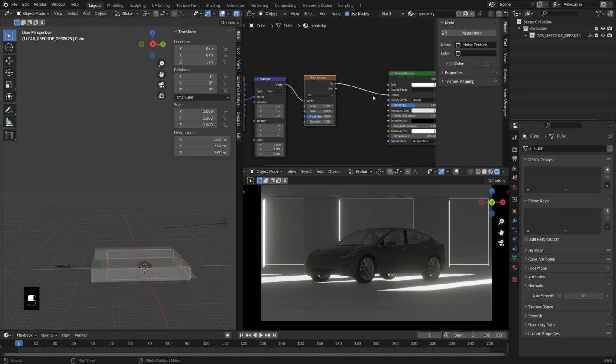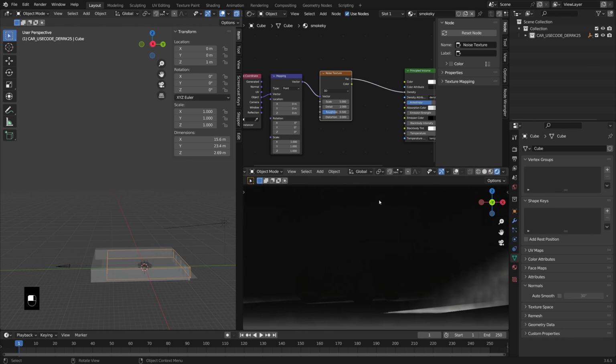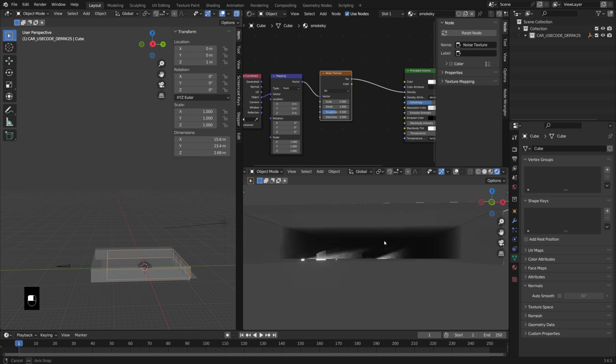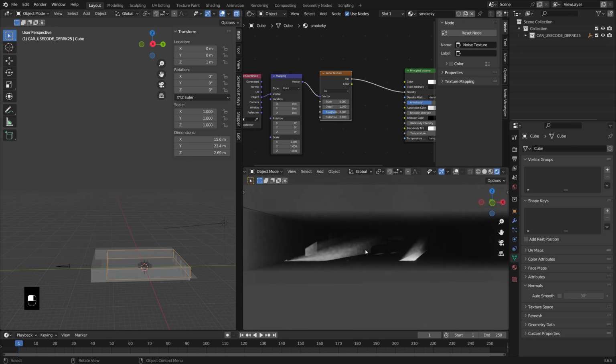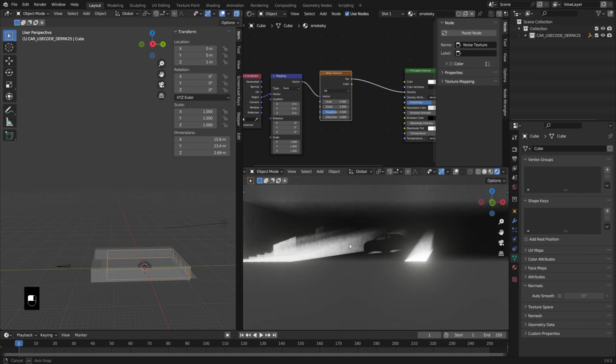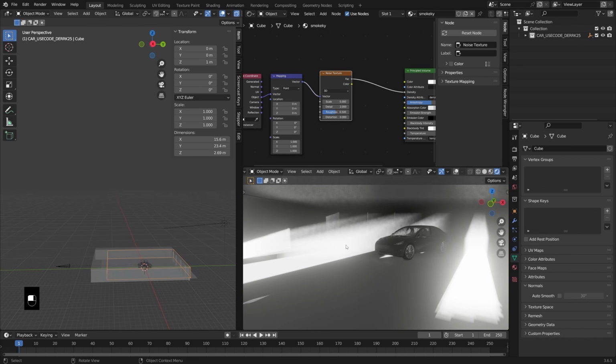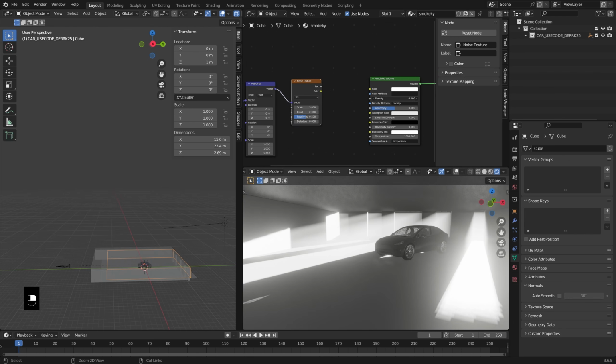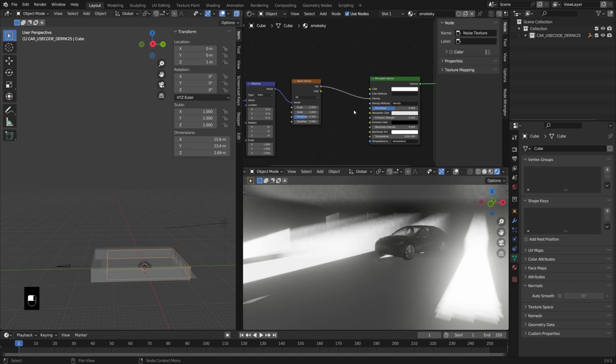You can cut that off. And right now this is going from, oh boy, okay, so now it's going from 0 to 1. We've got really dense areas. Okay, sometimes viewing the volumetrics in the viewport can get a little tricky, but you can see we've got our noise texture going on there. But right now this is outputting values of 0 to 1, and 0 is basically nothing, 1 is too dense. So we want to actually map those values to something lower.